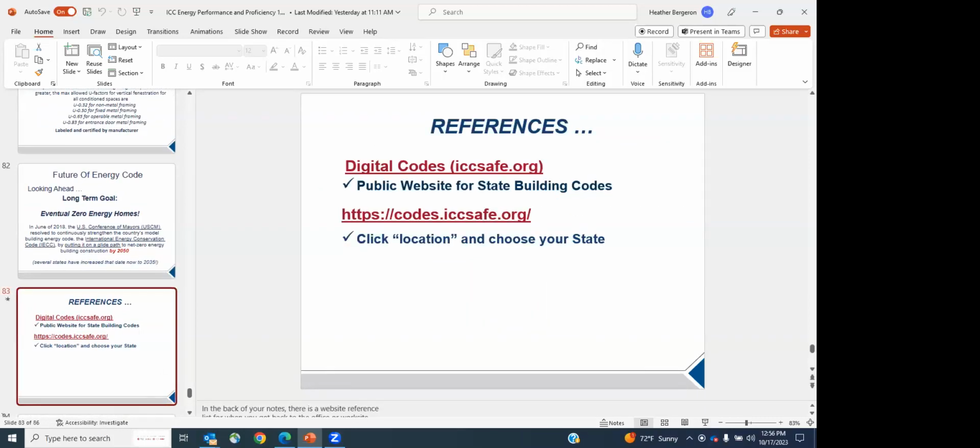And the reason for that is the film that you're putting on is on the interior of the house. You can't put it on the outside because it'll get damaged. So you put it on the inside, and then when the sun shines from the outside, it goes through and it's actually hitting that, warming up the temperature of the air or gas, argon gas, heating that temperature up in between. It can cause stress cracks.